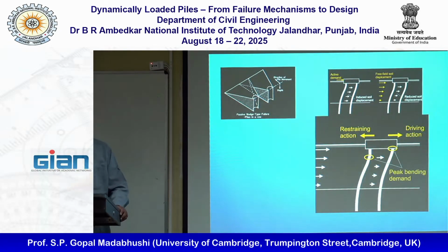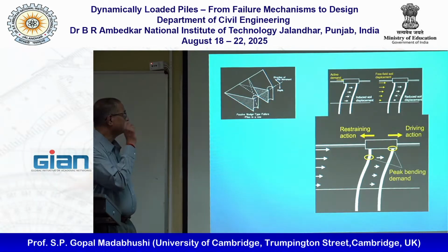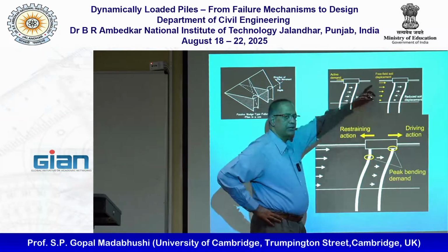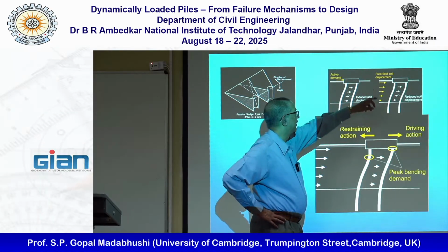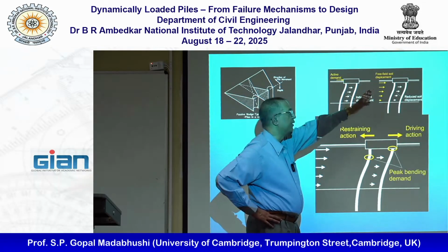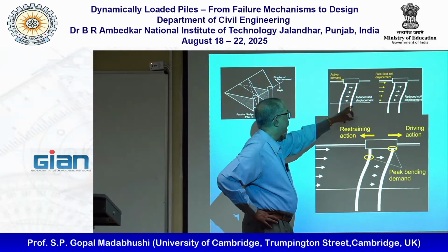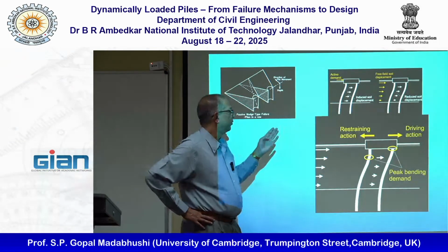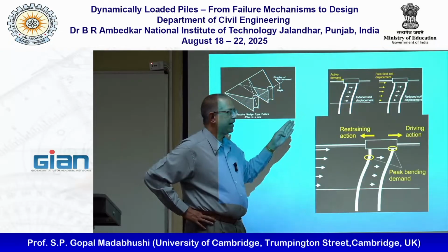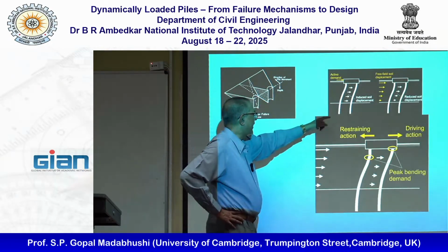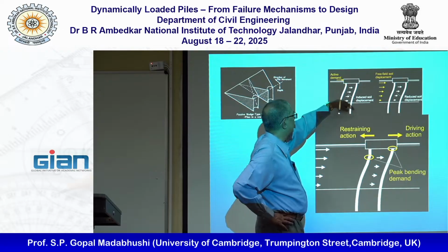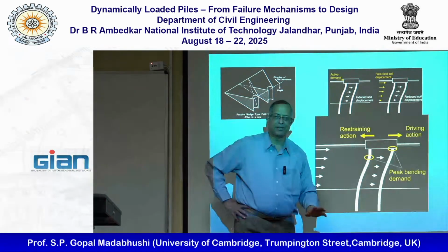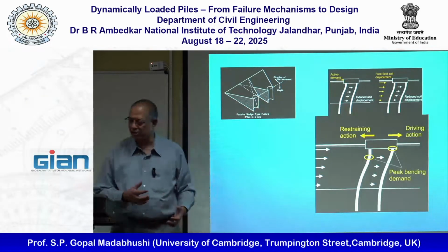There are also things like, if the free field soil is displacing with increasing amplitude towards the surface, the soil in between the pile group may move less because most of the load is being carried by the pile, right? So it will flex, say if it's a flexible pile, it does something like that. But these displacement vectors will be smaller than this. We don't need a centrifuge test. We can guess this is what happens.